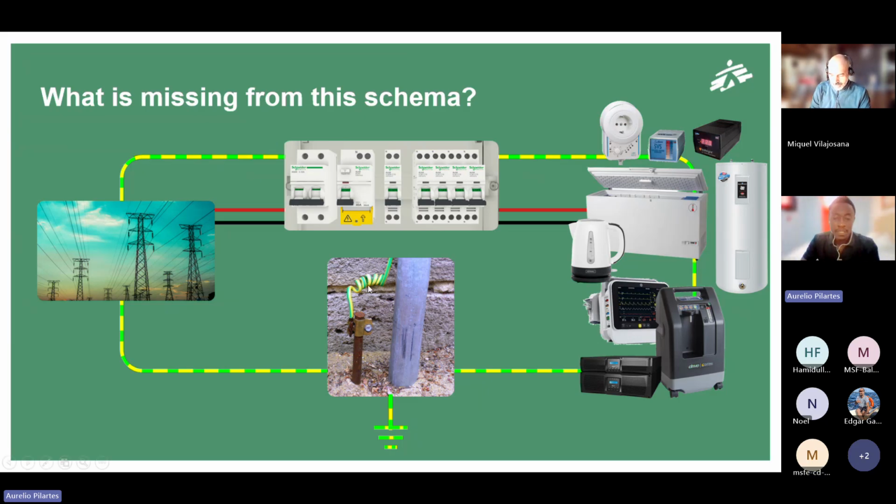For example, if it was an installation where this cable goes for a certain distance before going up to the cutting bar, which means the cable would go buried, then we should use a bare copper cable, the cable without insulation. This is the most suitable, because while your cable goes under the ground, you can increase conductivity by leaving this cable non-insulated in contact with the ground.